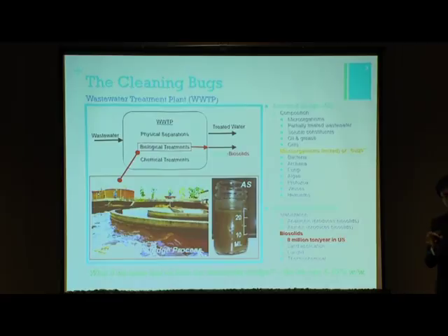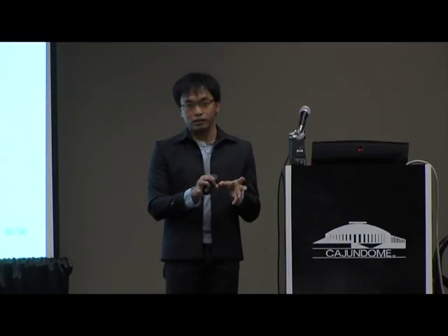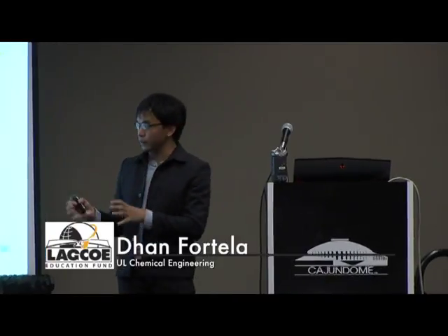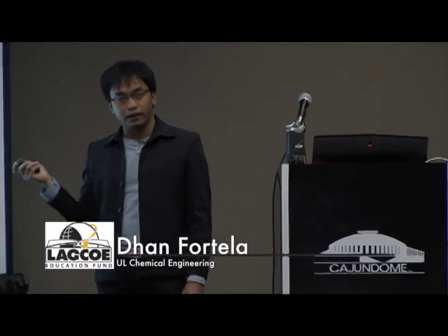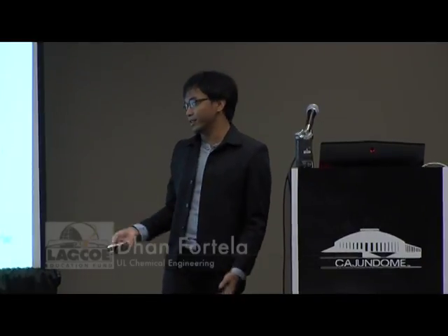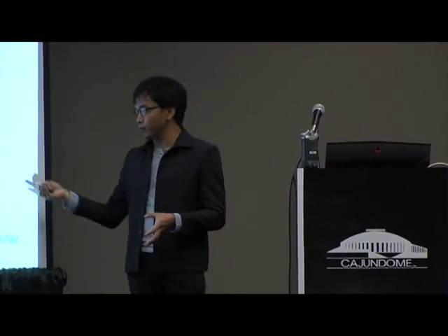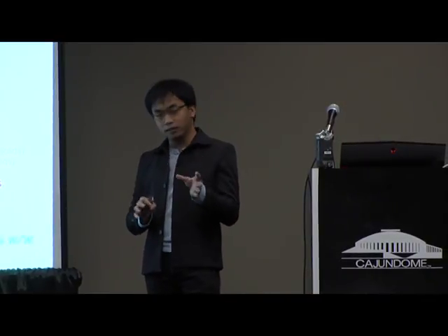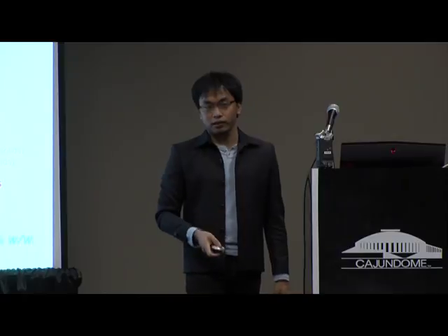Now, before this biomass of activated sludge and other sludges from our wastewater facilities are disposed out of the facility, they need to be stabilized. And there are two ways to stabilize them, producing the biosolids: anaerobic digestion or aerobic digestion. In the United States, we're producing around 8 million tons per year of these biosolids.